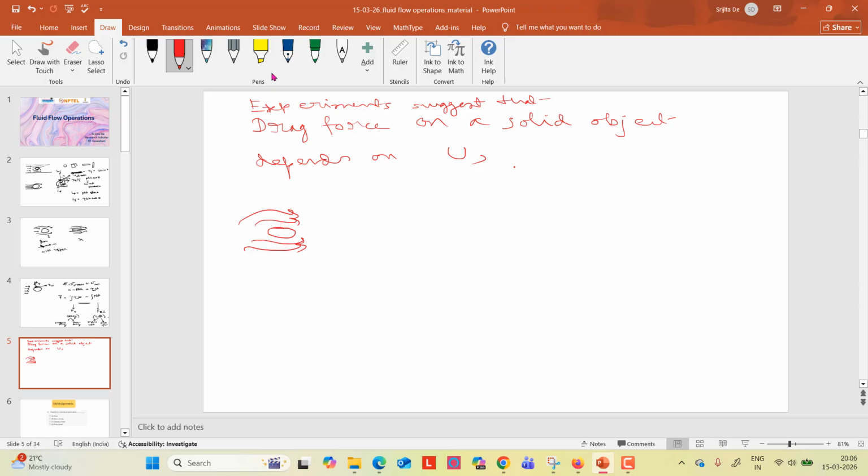It also depends on the density of the fluid, because the pattern will not be the same in the case of water, oil or honey. Similarly, it depends on the viscosity, and also on the size, which is the equivalent diameter. Now, taking a sphere, how can I define this with the Buckingham pi theorem?